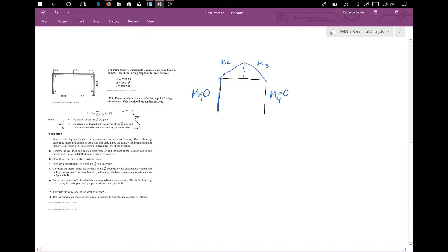All right, now that we've done that, I like to do this a little out of order than the way they do it. These are straight lines, so it's a very simple load. I'm just not good at drawing, but here are our moment diagrams, and remember this top part would be whatever that max moment is divided by EI.